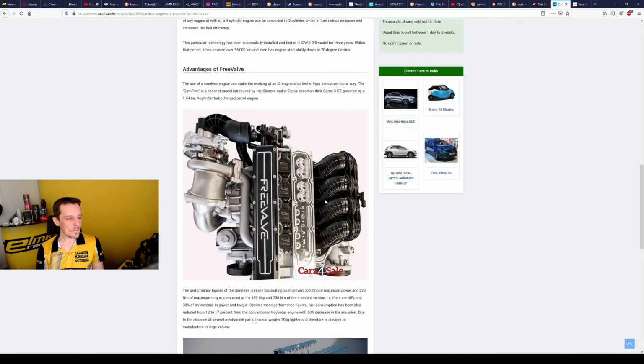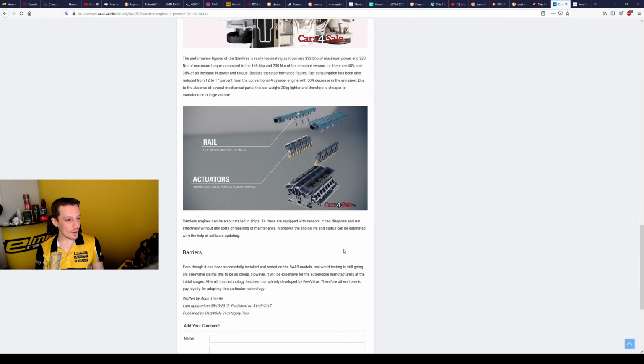So then you can get rid of the waste gates and stuff like that. You can just open the valve or direct more exhaust gas flow, bypassing the turbocharger, into the exhaust directly, so you don't need a waste gate for that. But then again, you end up needing more valve area per bore.